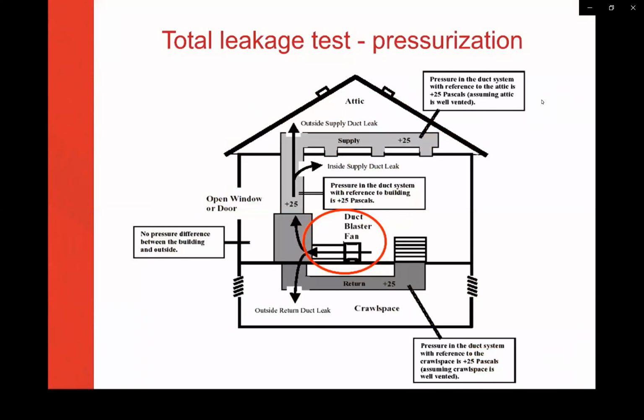So a total duct leakage pressurization test is what we're showing here. We've got the duct blaster fan blowing air into the duct system. If we bring it up to 25 Pascals, and that's the pressure in the duct with respect to the house, if that attic is well vented, then the duct to attic pressure will be very similar to that, especially if